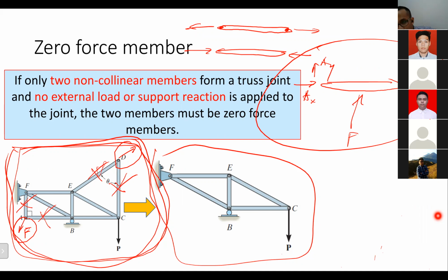It has a connection with that, because a truss structure only consists of two force members, and two force members means each is either under tension or compression, and the force can only be applied at either end. It cannot be applied in the body of the member.